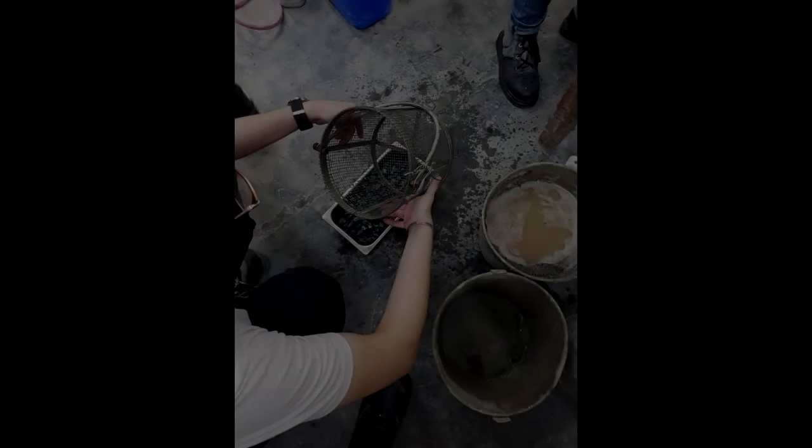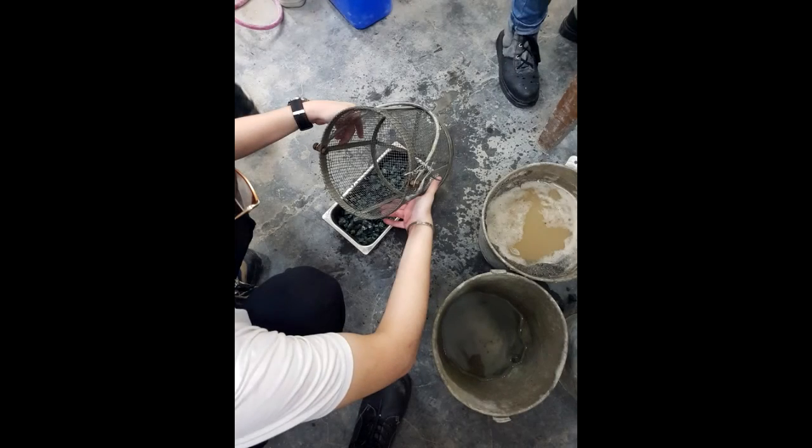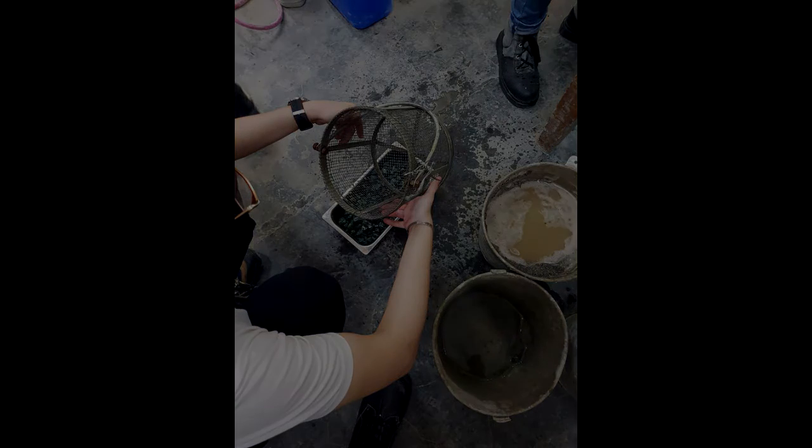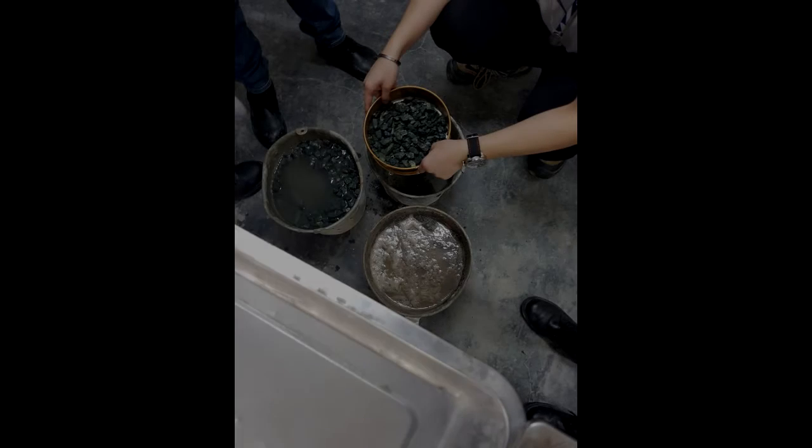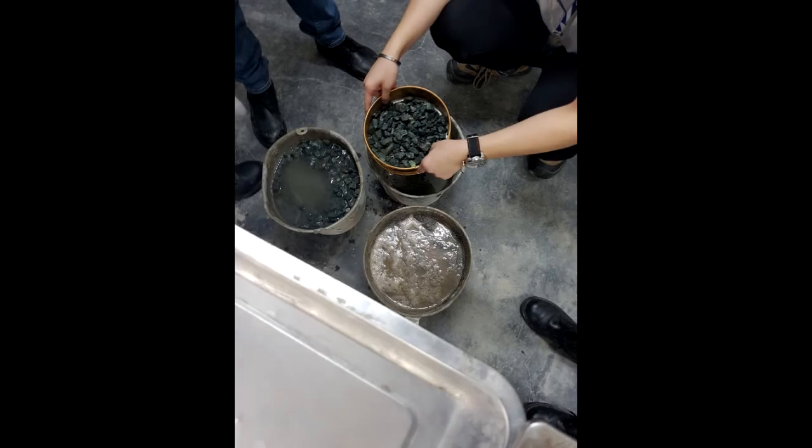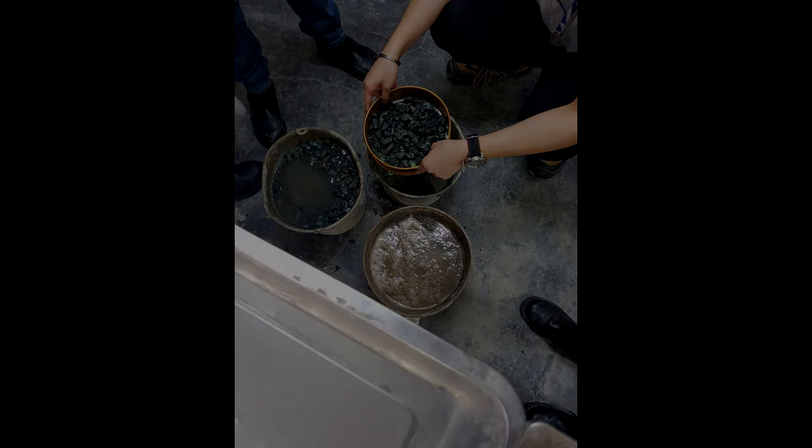For the first step, coarse aggregates were removed from the bucket and transferred on a 4.75 mm sieve to have the correct size of sample. Next, a piece of cloth was used to wipe the coarse aggregates before transferring them on a pan. This is the saturated surface dry condition, also known as SSD. The coarse aggregates were then weighed in water in a wire basket. Finally, the coarse aggregates were transferred back to the pan, dried in the oven to be weighed afterwards.